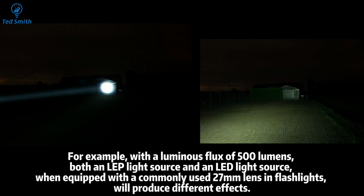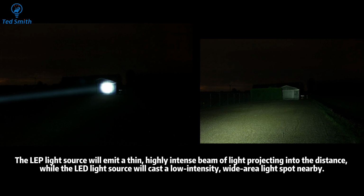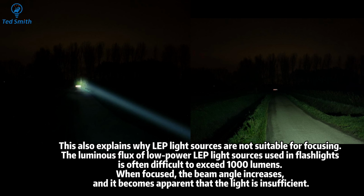For example, with a luminous flux of 500 lumens, both an LEP light source and an LED light source, when equipped with a commonly used 27mm lens in flashlights, will produce different effects. The LEP light source will emit a thin, highly intense beam of light projecting into the distance, while the LED light source will cast a low-intensity wide-area light spot nearby. This also explains why LEP light sources are not suitable for focusing. The luminous flux of low-power LEP light sources used in flashlight is often difficult to exceed 1,000 lumens. When focused, the beam angle increases, and it becomes apparent that the light is insufficient.